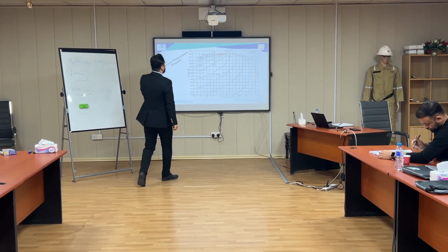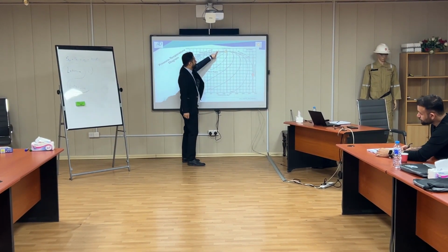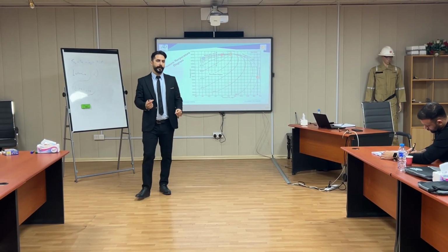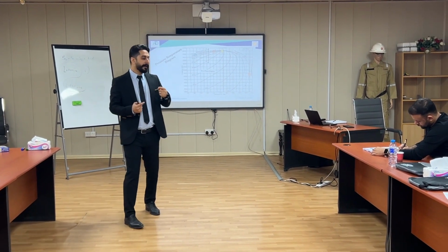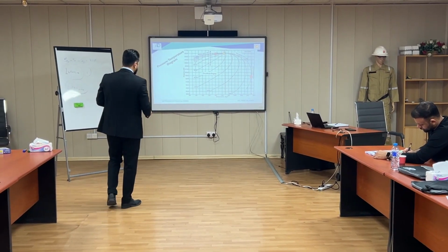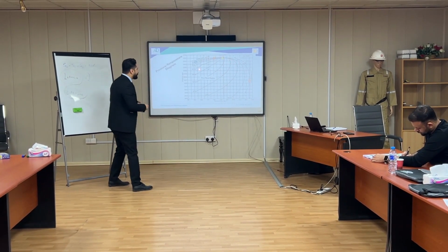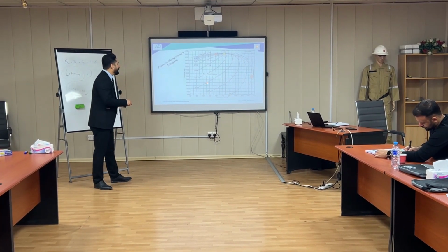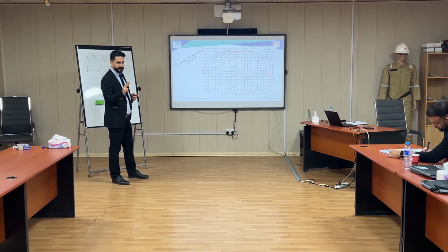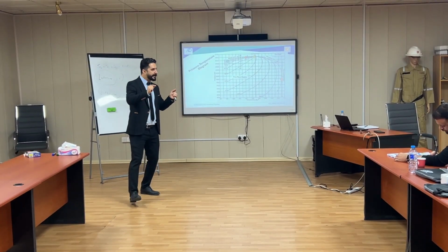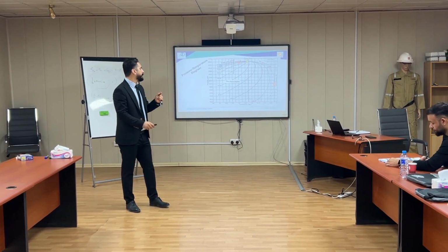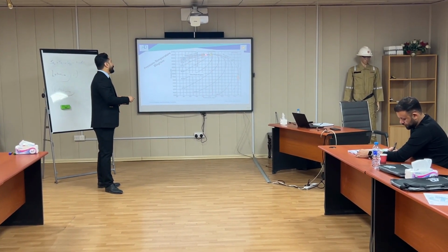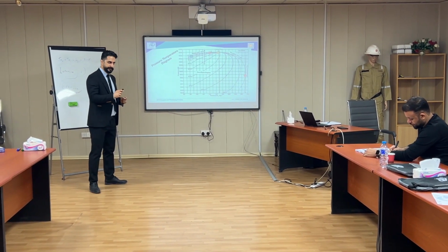But this point D is called Cricondenbar point. What does it mean? Look at it. We said that inside this envelope, we are going to have two phases. Okay? It means gas and liquid are available. But at this section, we are going to have just liquid.